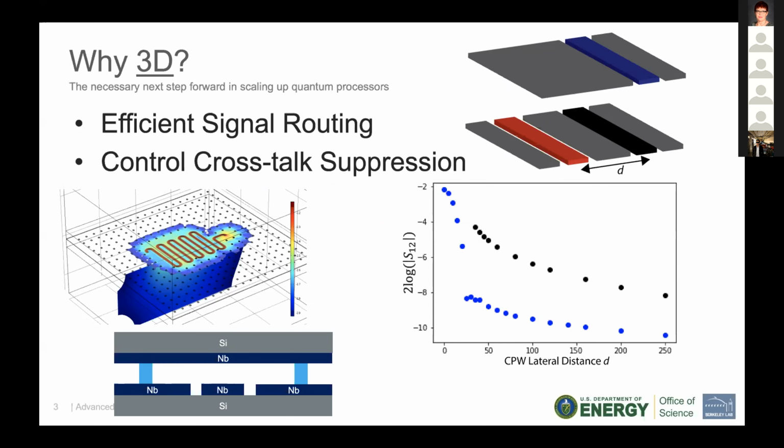Those two chips are connected together by these light blue superconducting channels, which are also reflected as these black dots in the finite element simulation domain above it. You can say that these superconducting channels form a lateral Faraday cage that localizes the fundamental mode's energy distribution around the meander resonator, so the extent is much smaller compared to its extent in the substrate.